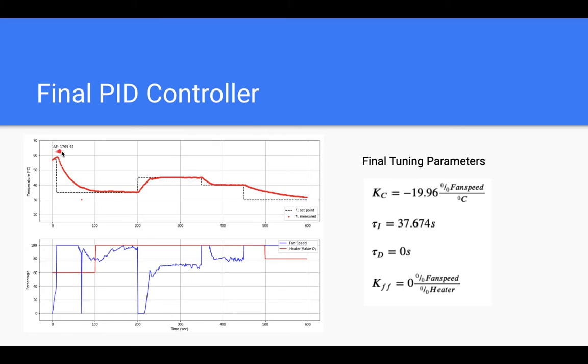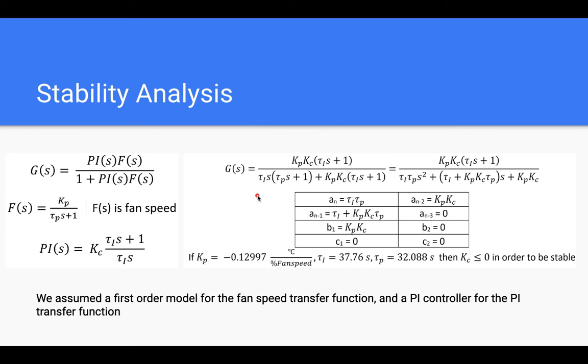As you can see right here with an IAE of 1770 basically, we were pretty good at controlling this temperature even with multiple set point changes and sizable heater disturbance value. Now here, you can see that it doesn't actually reach this temperature set point. That's because we're trying to get a set point of 30 degrees, and our ambient temperature is pretty close to this 30 degrees. So that cooling power that convection provides is pretty small at this point because that temperature difference is so small.